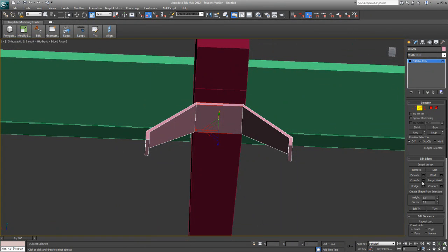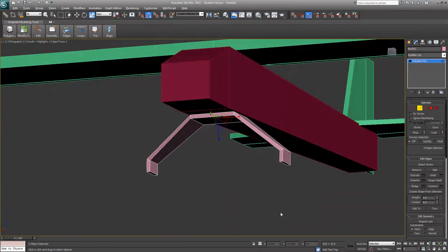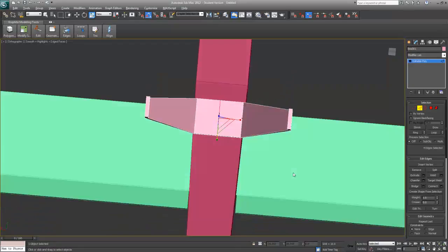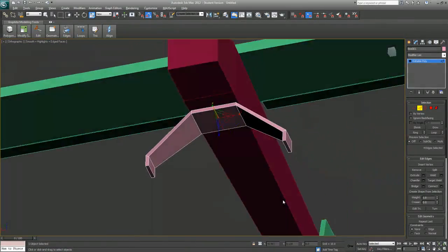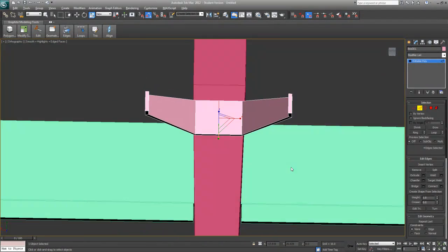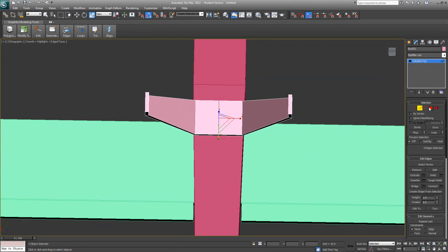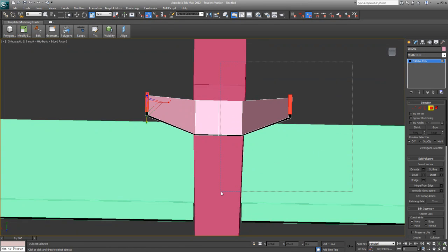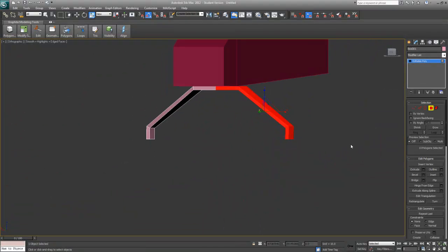Now, not far from the Extrude tab, we're going to have the Connect button. By default, this is going to be a single connection directly in the middle of all these lines. It'll connect all the way around. So, just clicking that button gives me a connection all the way around. That's good. So I'm going to select all of the faces on this side.